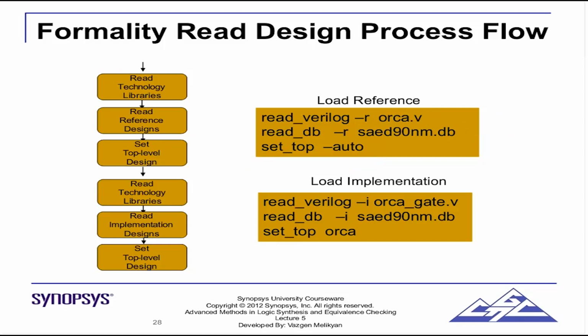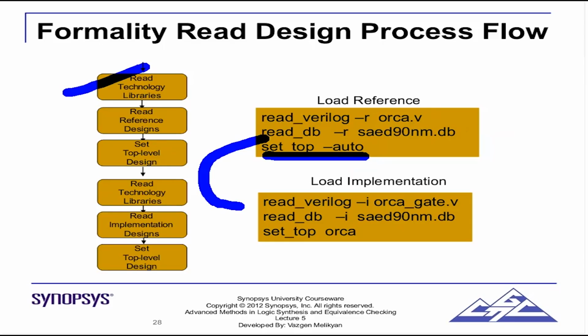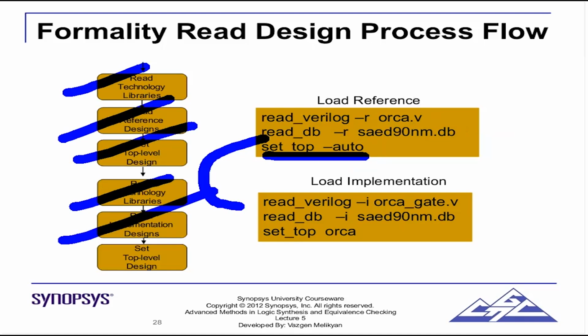It is very important before switching from reference to implementation. This step is very important: set top. Again, you read the implementation. The only thing that changes is the -i option. You read the same library if you are using the same library across both the designs. Again, set top. So read technology, read reference, set top, read technology again, read implementation, set the top level.